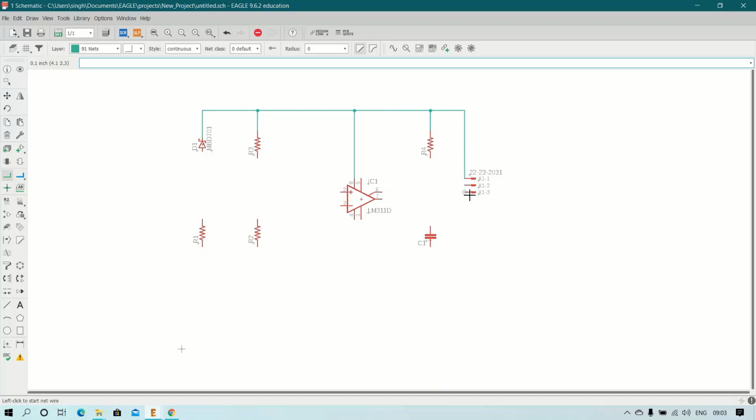Next we will connect the ground voltage, same, to all the components that need ground. For this resistance, pin number 4, and also the emitter pin of the voltage comparator. Because we are using this in common emitter form, we will connect the emitter terminal to the ground, and this capacitor.